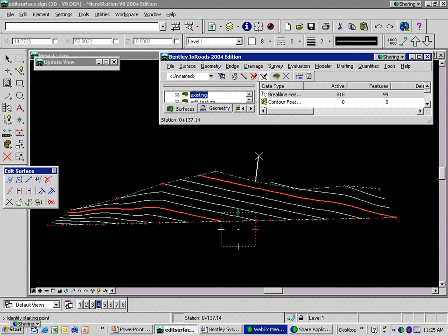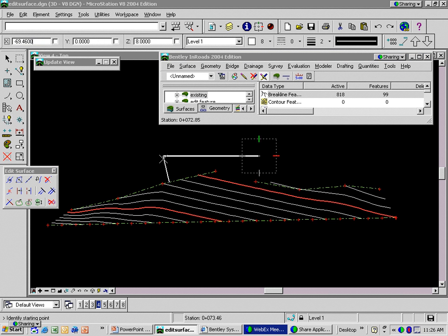So right now, I'm just going to delete from here, partial delete to there. If I used the element command, the snaps for element, where I could choose this feature and delete from here to there, new vertice points will be where that discontinuous section is in that feature.